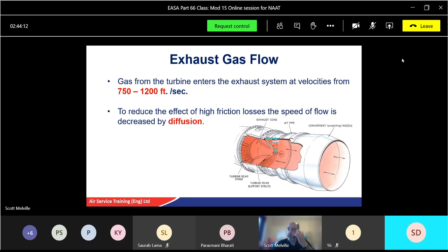Yeah, the pressure, yeah. If you've got the fast moving air coming out of the turbine, which goes over the cone, I'm pointing to the screen here, you can't see me pointing, but if you've got fast moving air, you've got low pressure. Well, if you've got low pressure on the outside, inside the cone, the slow moving air is going to be high pressure. So the high pressure is going to win. It's going to try and expand the cone. So by having a hole in the tip here, that equalizes the pressure outside the cone and inside the cone, so it doesn't expand out.